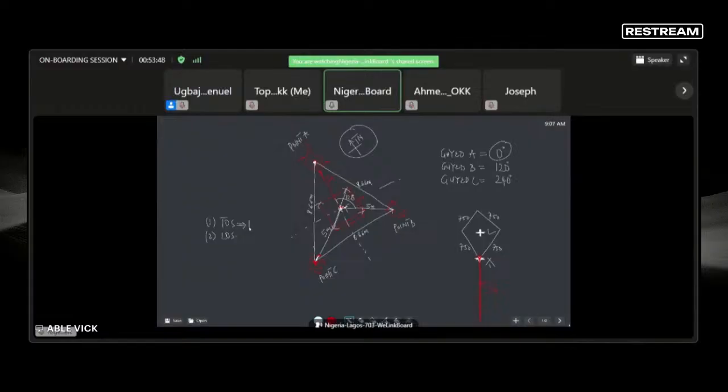Once you've confirmed the team is on site, you also need to confirm that coordinate, confirm LOS. So when you get to your point, the proposed site location, send that coordinate back to the survey team to confirm that that point is okay for deployment. After they've confirmed that you're on the right spot, then you can start your setting out. If you're not on the right spot, you need to continue your journey to the right location.